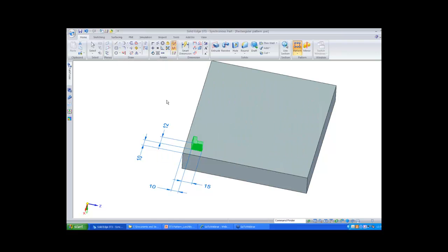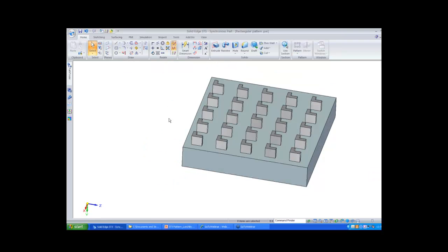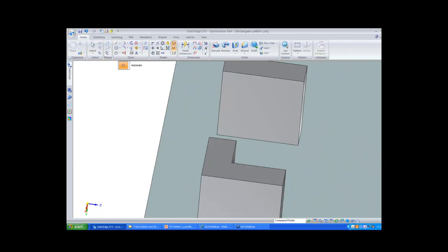All right. So what if I have a feature on the top face? So what I'm going to do is just create a feature on the top face. Let me unlock myself. And we'll just sketch a circle on this top face. With the help of relationships, I can quickly snap this to the endpoint.